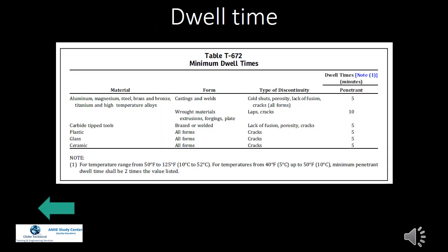Dwell time. Minimum dwell time after penetrant application is 5 minutes, and maximum time is 10 minutes at 10 degrees to 52 degrees Celsius. But for 5 degrees to 10 degrees Celsius, the dwell time will be double. Please see this chart for dwell time.